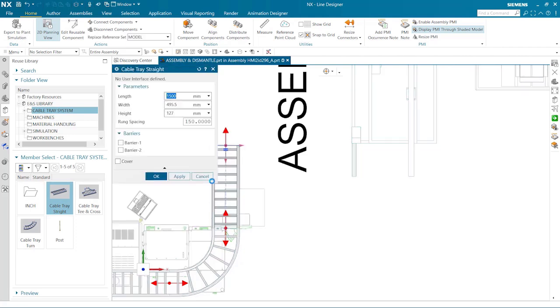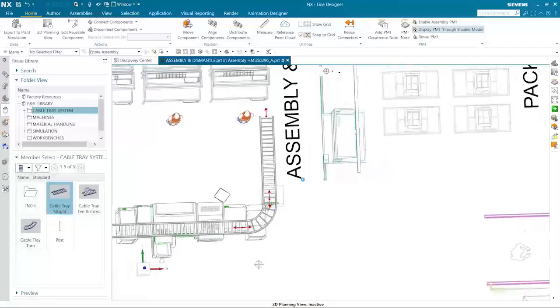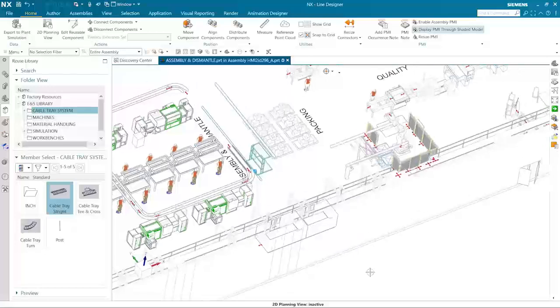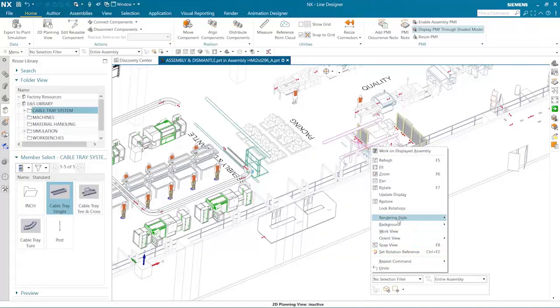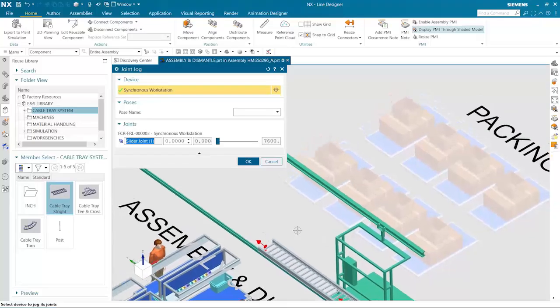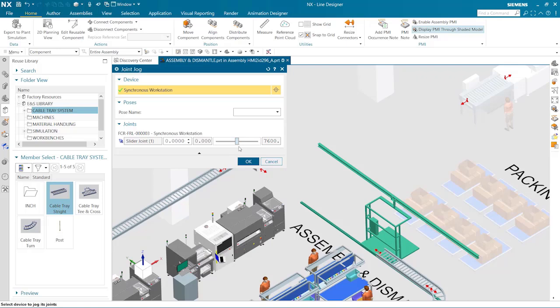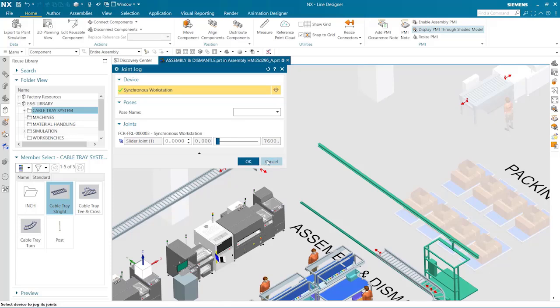In this case, changing length is done directly from the parametric menu. The layout also supports moving mechanisms to their different positions. The ability to do so can mean not having to relocate the equipment after discovering it collides with objects on the floor as it moves.